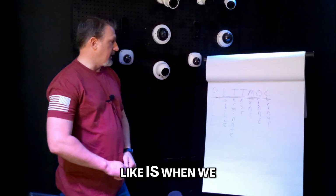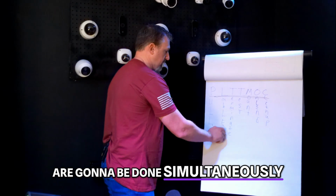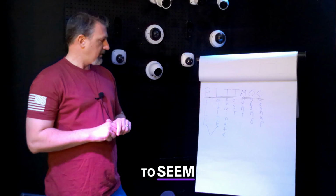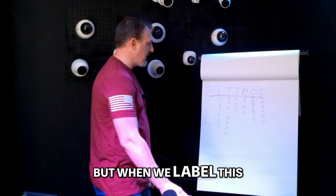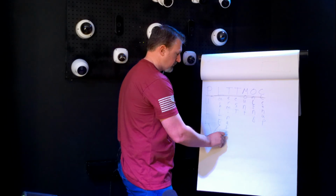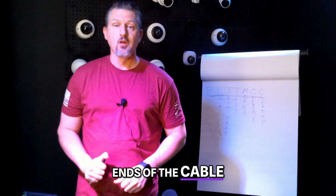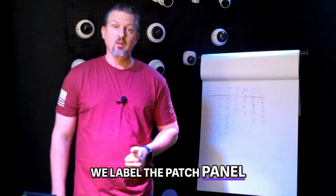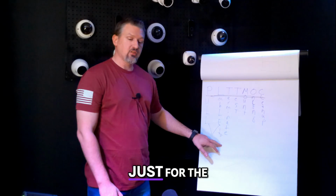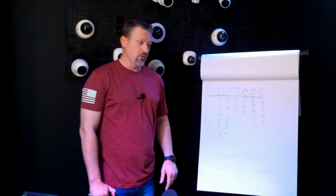So what this looks like is when we pull the cable, these two things are going to be done simultaneously. And this is going to seem a little overkill, but when we label this, we want to use 4. So we label both ends of the cable, we label the patch panel, and we label the device. We do this not just for the installation, but we do this for the maintenance coming down the road.